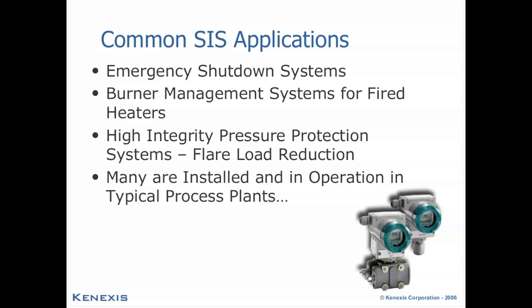We see a lot of safety instrumented systems on fired equipment, including burner management systems and flame safety systems, as well as systems that are designed to specifically operate at a high level of integrity and protect systems against overpressure. We call those high integrity pressure protection systems, as well as a variety of other systems out there in process plants.